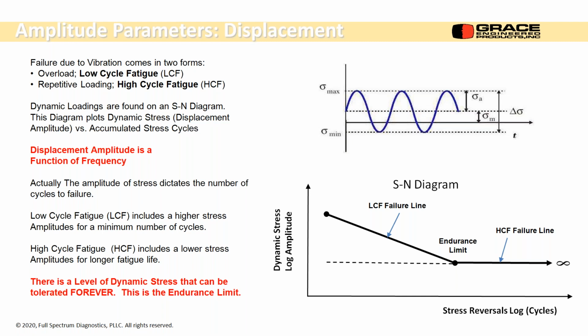Low cycle fatigue can usually be designed out, but there's something that's changed recently in the power industry. They're not using main coal power plants anymore as base load. They're using a lot of them as peaker plants. And you have all these really big pieces of equipment, a lot of forced draft and induced draft fans, and they're not made to start and stop. You start them, and 2 years later, you turn them off at the outage. But now they're starting and stopping every day.